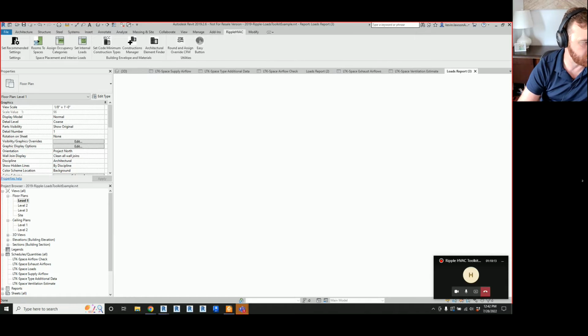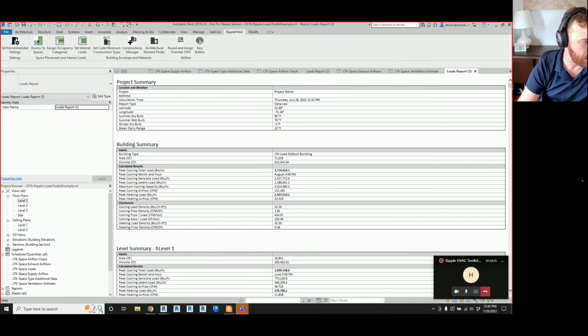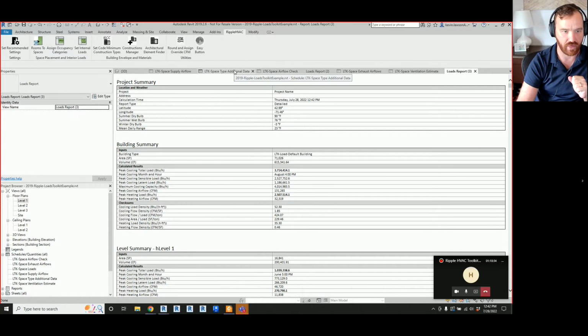Okay, from a Revit 2022 standpoint, how are you pushing your construction overrides into the EnergyPlus calculation? I have not dug into the EnergyPlus integrations too deeply, but I'm pretty certain the construction overrides work the exact same way. If it's overridden, the analytical energy model will pull those space constructions, just like it pulls the internal loads from the spaces.